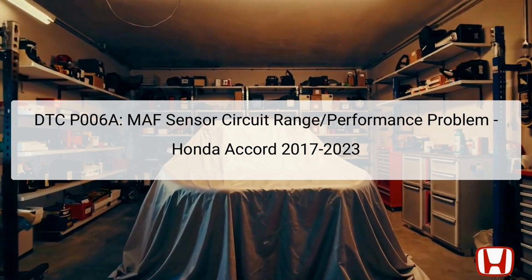This sensor is crucial because incorrect readings can lead to poor engine performance, higher emissions, or even engine damage if not addressed. The location of the MAF sensor is typically between the air cleaner assembly and the intake manifold. Additionally, this error could coincide with other potential DTCs such as P2073, P2074, P2228, and P2229, which should be addressed first if they are present.